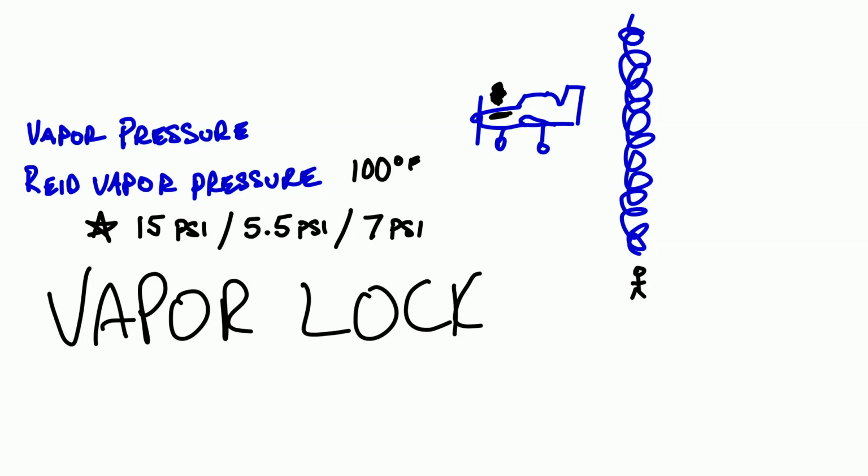And by the way, if we're talking about fuel metering systems and fuel systems, the line of demarcation for an aircraft between the airframe fuel system and the engine fuel system is typically going to be where the fuel enters the fuel metering device or something directly connected to the fuel metering device. So if we happen to have an engine driven pump that's attached to the engine, a lot of times that will be considered part of the engine fuel system, and that's where that starts.